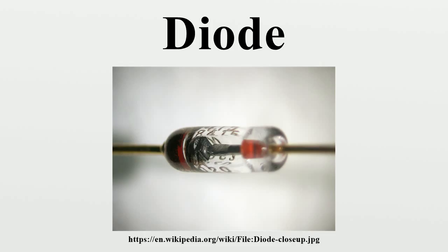However, diodes can have more complicated behavior than this simple on-off action, due to their nonlinear current-voltage characteristics. Semiconductor diodes begin conducting electricity only if a certain threshold voltage or cut-in voltage is present in the forward direction. The voltage drop across a forward-biased diode varies only a little with the current, and is a function of temperature. This effect can be used as a temperature sensor or as a voltage reference.